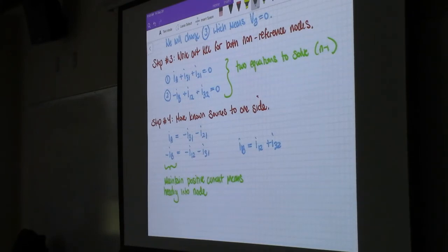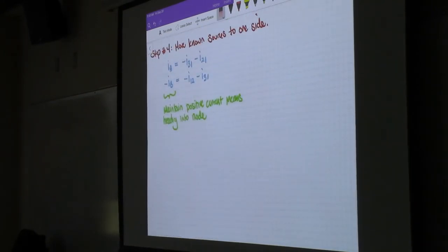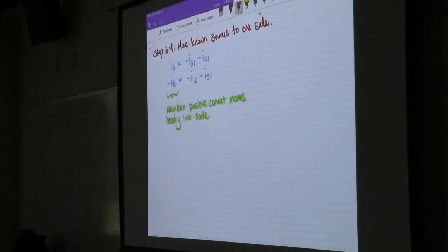So you just look at the circuit and you go straight to the matrix. When we do nodal analysis by inspection, there's certain assumptions we make, and one of them is that the current's positive when it's heading into the node. So in order to make what we're doing now agree with what we'll be doing then, let's just go ahead and try to stick with that.